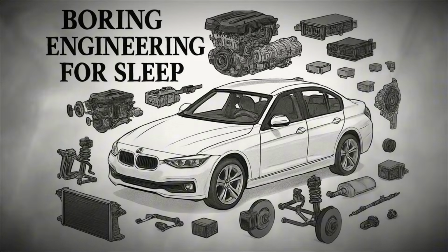The most common type of engine in cars is the internal combustion engine, which burns fuel and air inside a chamber to create controlled explosions that push pistons downward. These pistons are connected to a crankshaft that converts the up and down motion into rotational motion, and that rotation is the source of mechanical power for the car.